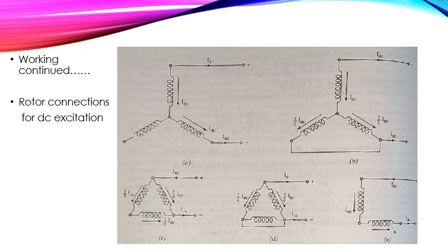A very short air gap, such as expected in a plain induction motor, would result in a very heavy armature reaction when operating as a synchronous motor, because the total field ampere turns would be reduced for a given number of armature ampere turns.